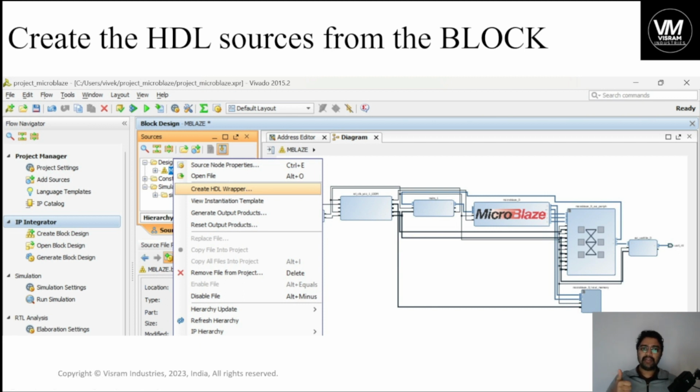First step, create an IP block, and second step, run block automation by adding the elements. Third step, connecting them, run connection automation. In the fourth step, we added the UART lite interface and also changed the names of the clock and reset ports to clock_50 and reset_n.